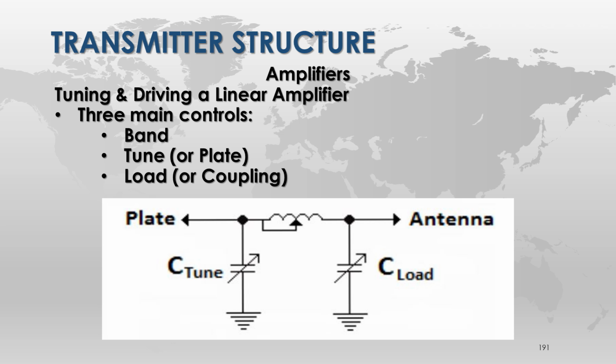Now here's the part that they're not telling. There's actually 4 components here, not just 3. The one you are not seeing is this guy. Sure, it's right there. It says it. Yes, that is a fixed radiator. What you are doing is you are tuning these 3 components to allow this fixed radiator to do its job. You're making a 4-component resonant circuit, not a 3-component. But look at that, there's nothing yellow up there either. What Dave's talking about is whether that's a tuning circuit in your amp or an outboard tuner. It's all part of the antenna system.